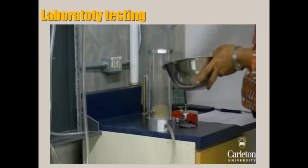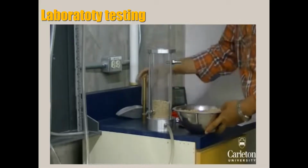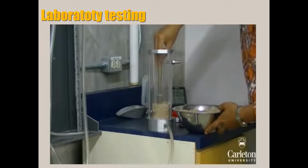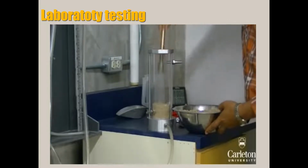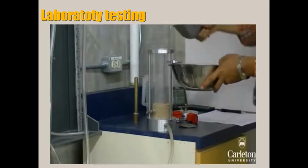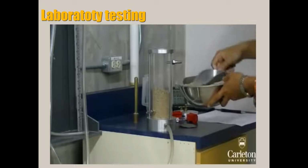Fill the cylinder with the soil sample. Split the soil into about 3 layers, and compact each layer with a hammer, like this. If your objective is to determine the conductivity at a specific density, measure the mass required given the volume of the cylinder, and compact the sample enough so that it completely fills the cylinder.